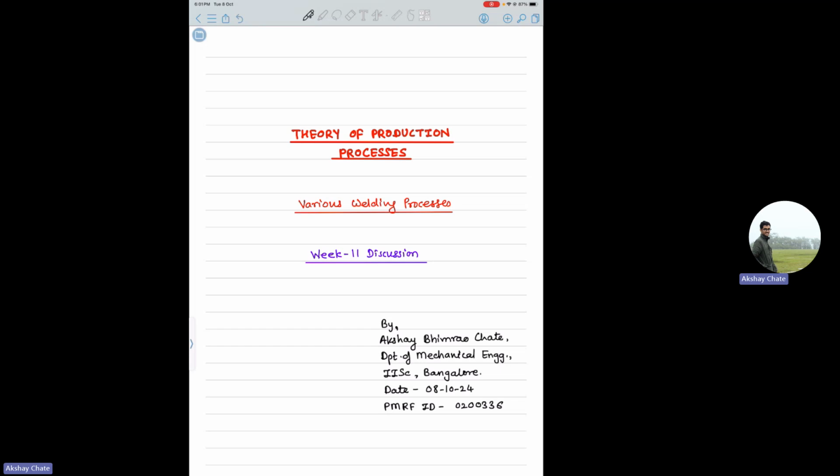But the problem is, because of the corrosion arising due to the residual stresses, even ductile materials sometimes can fail like brittle materials, which is called brittle fracture, and that's not a good thing, because we have discussed this previously also. When some ductile material is expanding or getting stretched under the action of various kinds of loads, you will have some time to react.